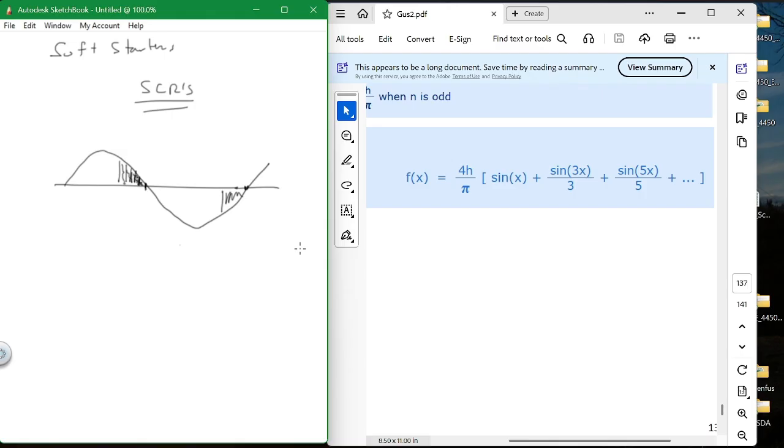But anyway, that's an application where you don't want to misuse soft starts. You don't want to use them as a cheap version of an inverter, because they don't work. You can soft start a motor, but you can't control the speed of it. Once it takes off, it's going to go. It's just going to keep going faster as it goes.